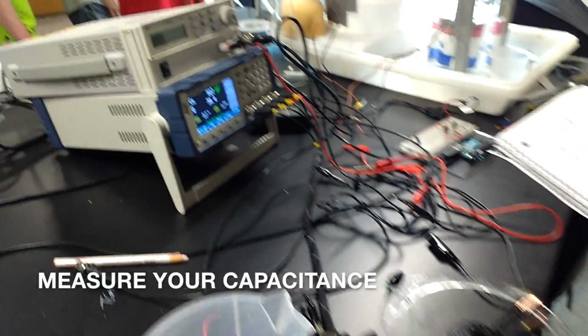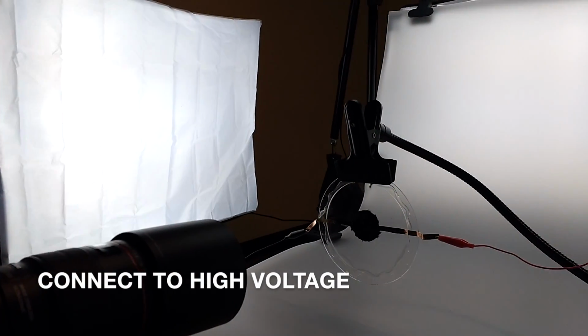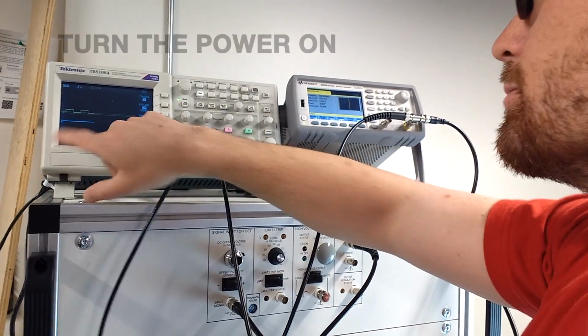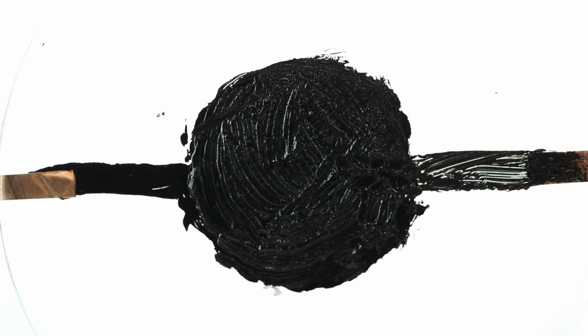Measure your capacitance with an LCR meter and compare it with your calculated value. Clip electrodes to your copper tape leads. Before turning on the amplifier, set up your function generator. When you're ready, turn the power on. At 7 kV, maximum areal expansion achieved is 50%.